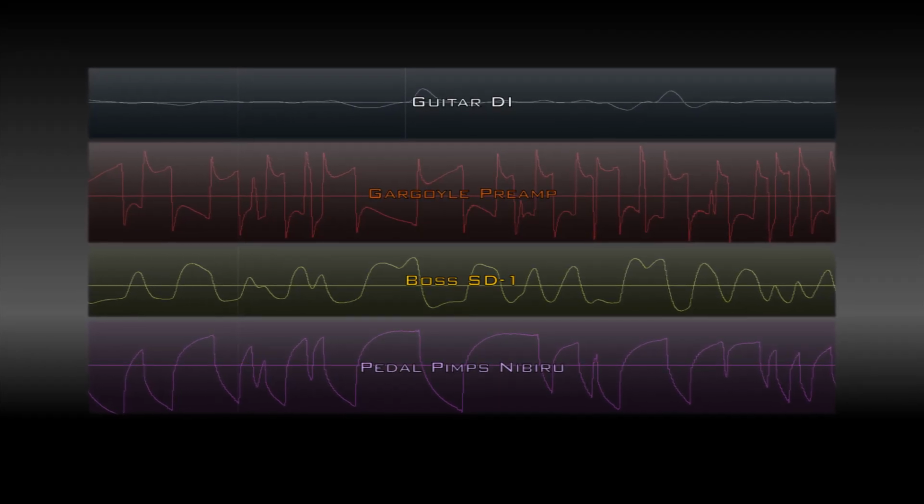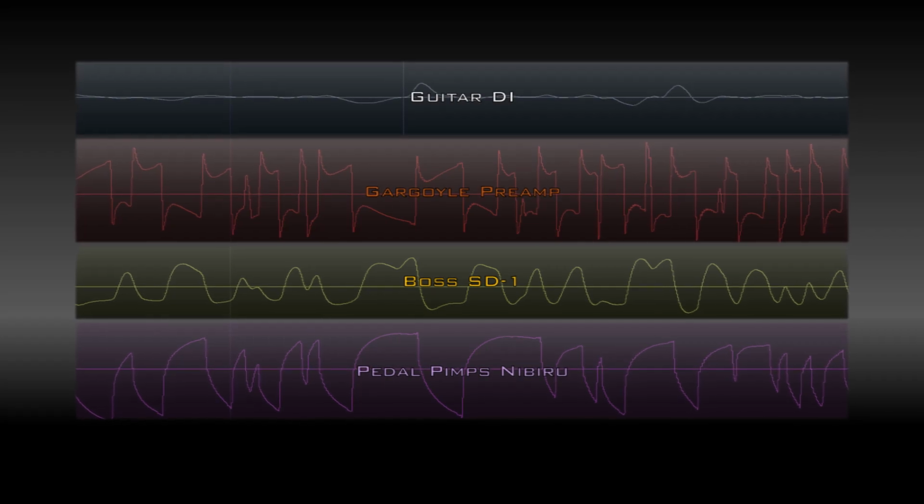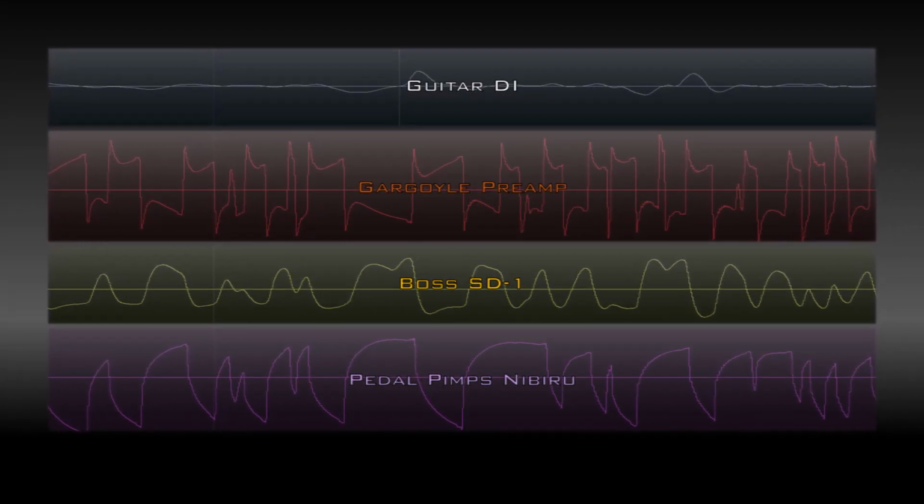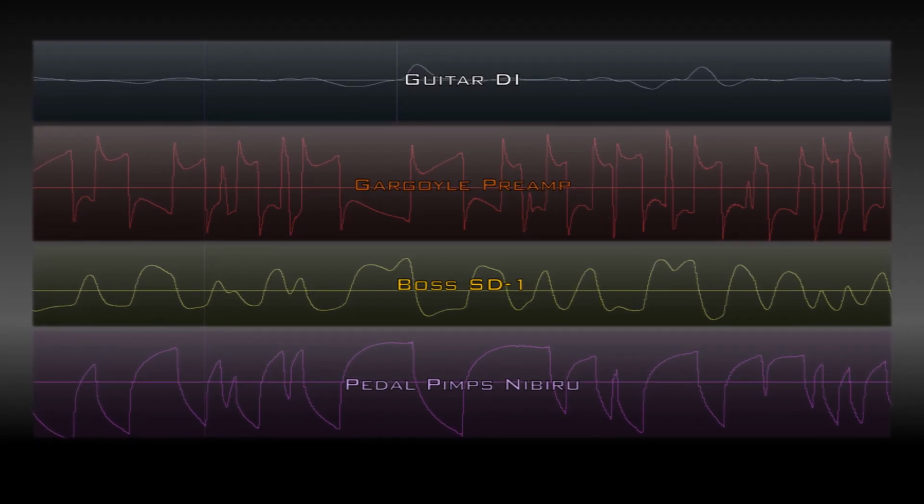Of course, clipping isn't quite that simple. Not only do you have hard clippers and soft clippers, but the threshold on each side of the waveform isn't necessarily going to be the same. So oftentimes tube amplifiers are associated with having asymmetrical clipping, especially of the Marshall variety, which sounds more aggressive and oftentimes more harmonically rich and full to our ears.